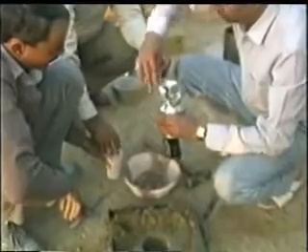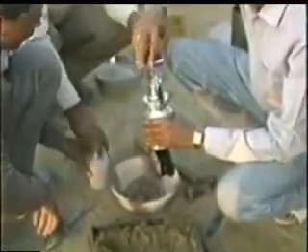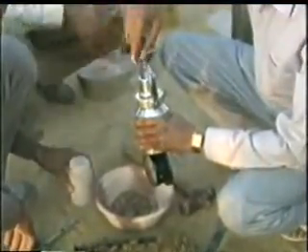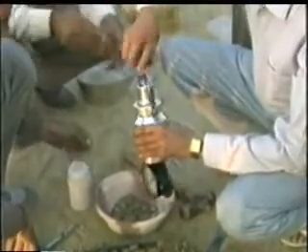The compacted soil subgrade is tested for its moisture content by rapid moisture meter and its value compared with the desired optimum moisture content.